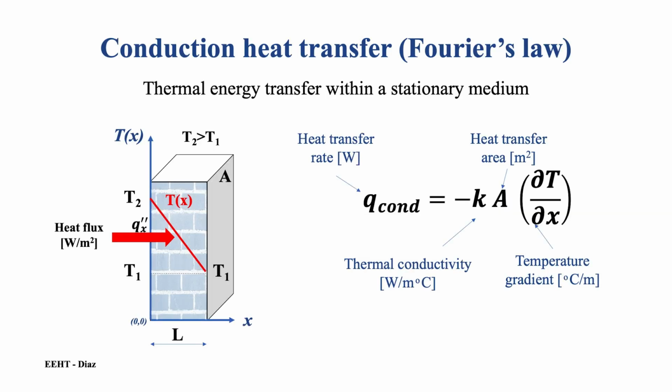Conduction heat transfer is the transport of thermal energy within a stationary medium, which can be a solid or a fluid, as a result of a spatial temperature difference. The conduction heat transfer rate is proportional to the material's thermal conductivity, area of heat transfer, and the temperature gradient.